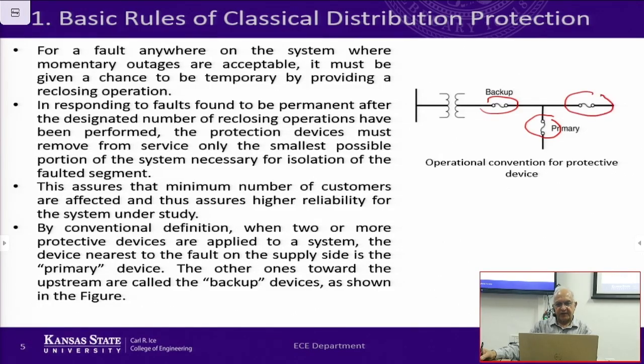Power is flowing in this direction. So for a fault here, this fuse is the primary device because it's the closest to it.